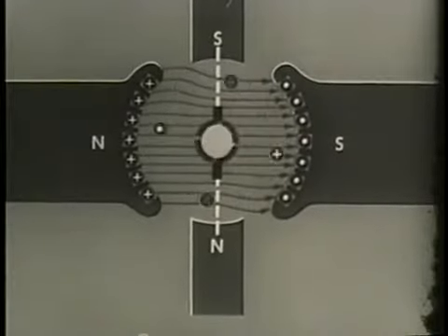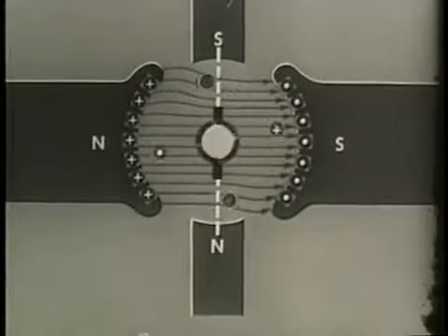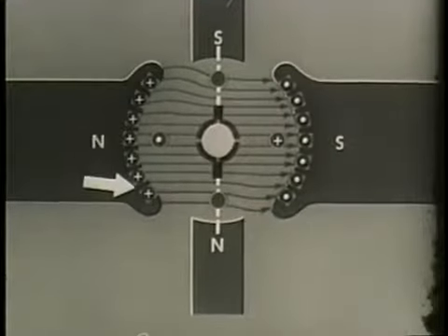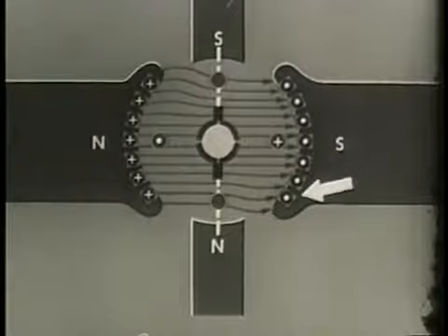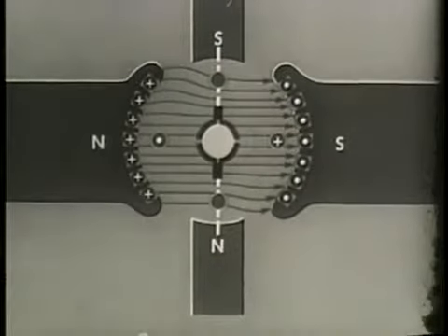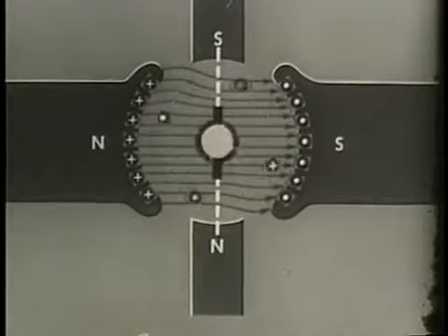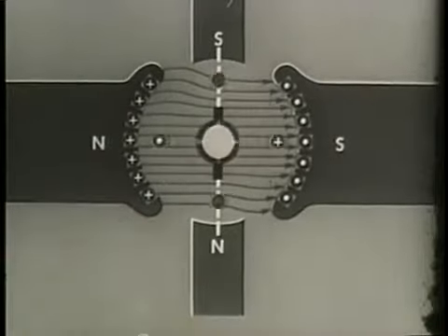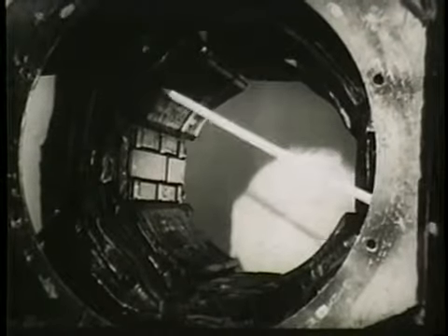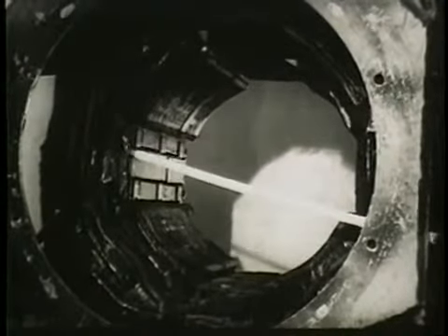In addition, to further counteract armature reaction, windings called compensating windings are sometimes placed in the main pole faces. The current in these windings is armature current flowing in opposite direction to the current in the armature conductors. Magnetic fields in DC generators may be produced by electromagnets or permanent magnets. Permanent magnets are used in relatively small devices like a field telephone ringing generator. In larger generators, the field is created by electromagnets.